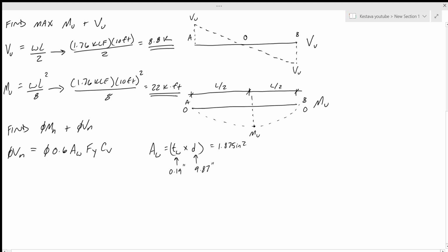And that's because for shear, the web is the only member that's transferring shear through your member. So if I kind of dash it out over here, the portion of steel that you get to calculate that transfers shear is actually that right there. So you can take advantage of all of that. And so that's what we've done here. That's that outline there. That is your Aw.